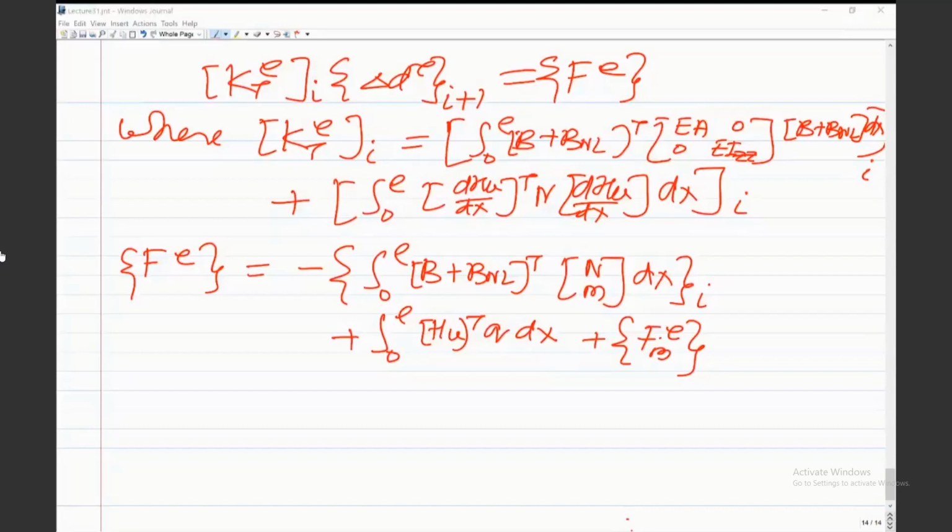Sir, if we are considering it as a small deformation problem where we are not considering geometric nonlinearity, then do we need to consider it? No, then you need not consider that. If there is only a transverse load, then you just need to consider only V. U naught will come out to be actually 0 even if you include it for a linear problem under transverse load. Okay, sir. Thank you, sir.